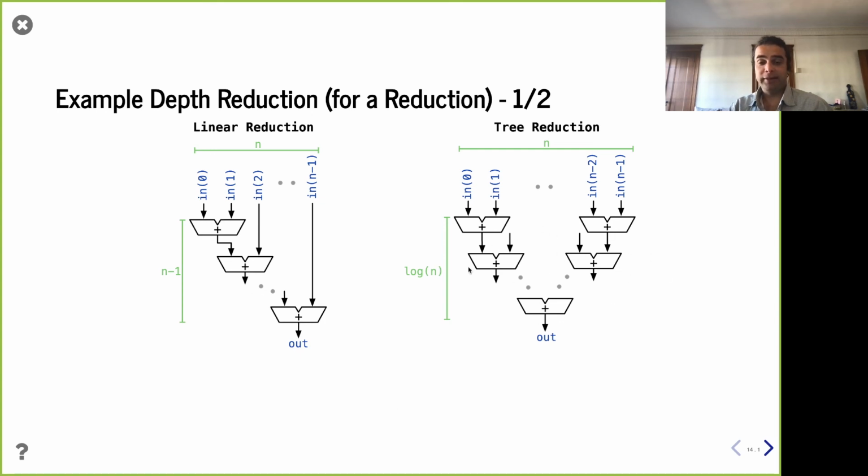And the interesting thing with the tree is that it actually doesn't require more hardware, right? If you think about it, part of what linear is getting wrong is that for each additional adder, you're only getting one more input, versus with the tree approach, you're putting 2 inputs per adder. Yes, you're kind of funneling them together, but it actually takes about the same number of adders, right? And so the tree seems great. So why wouldn't the tools just automatically do the tree?